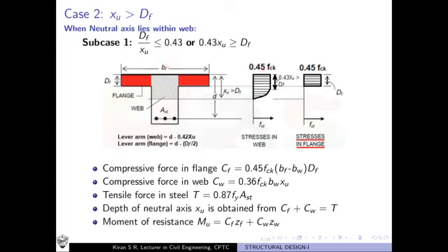I am drawing it here. Okay, so this initial portion above the neutral axis is a parabolic region, after which there is a uniform stress equal to 0.45 fck. Now you see, the initial portion of the stress in the concrete is a parabolic region, after which it goes as a uniform distribution.